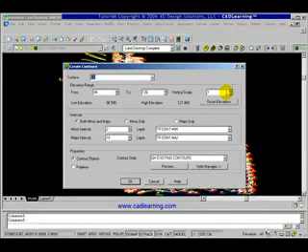We have one final dialog. We verify the surface is EG. We see the range of our contours based on the data. We have options to change the intervals. We'll keep it at 2-meter interval for minor contours and 10 meters for major contours. We'll accept the layers as shown in this style. We'll click OK.